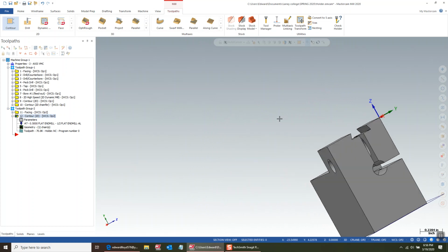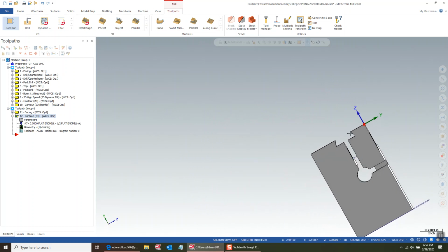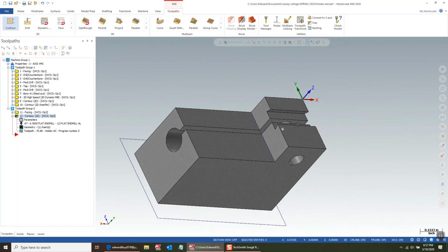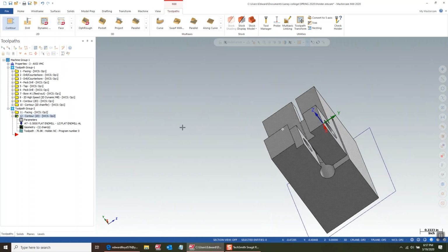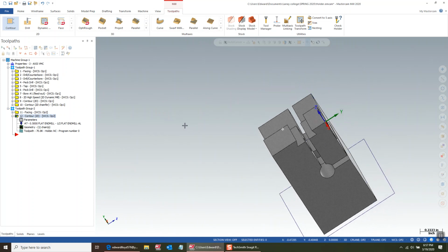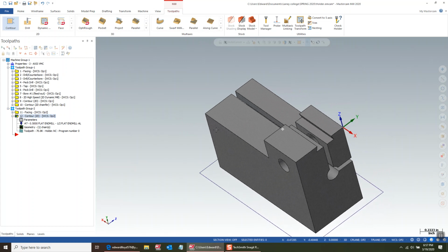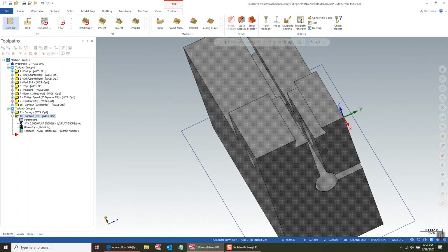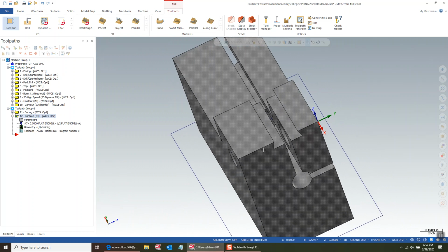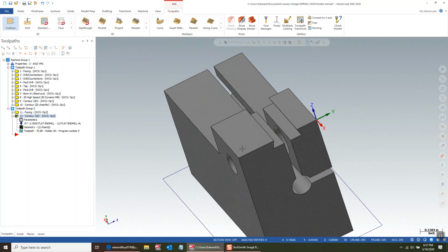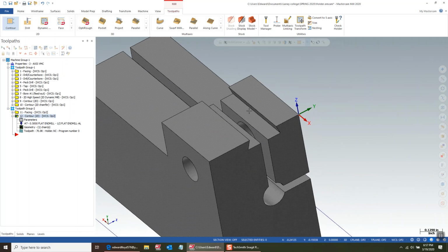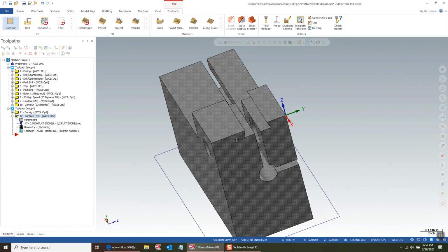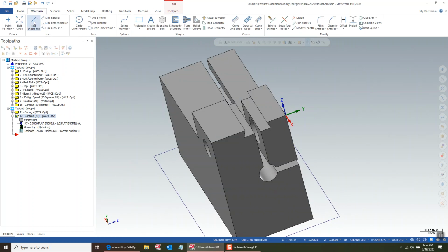And next, we'll take care of this dovetail cut. This is the area that actually holds the indicator when this thing is finished. So what I'm going to do for this is I want a line that goes right down the middle, just because I know I don't want to use the actual solid geometry, so I'm going to go to wireframe, click my line endpoints,